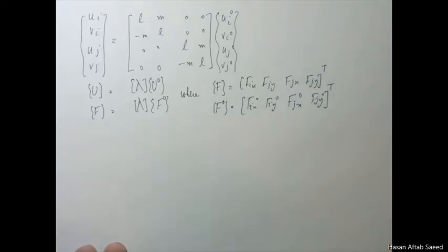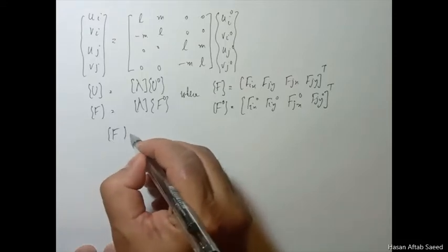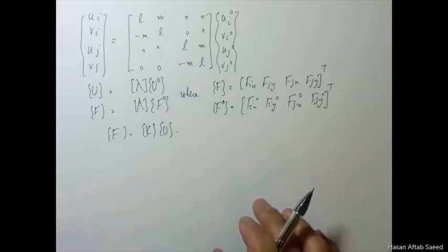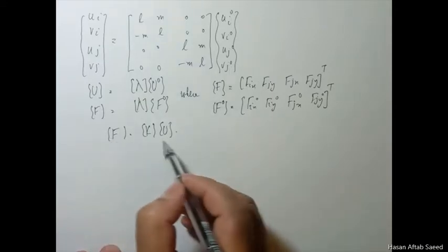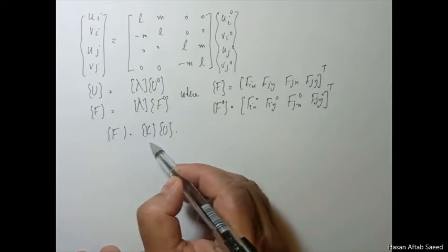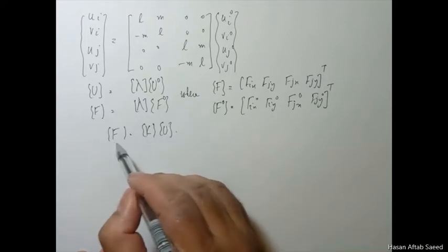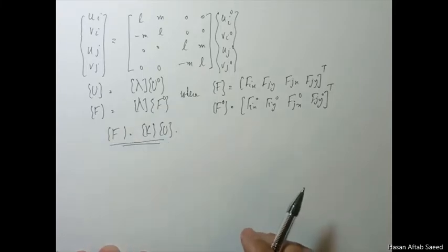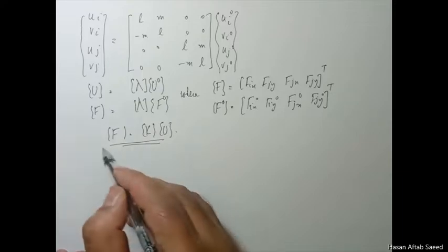Now we are very familiar with this equation in all FEM problems. Ultimately we get this solution. What sort of shape this takes, obviously it depends on the problem, but this F is equal to KU, this is basically the equation for a spring. And all systems, ultimately when you talk about stress analysis problems, especially problems where we are just talking about equilibrium problems, we are not talking about dynamic problems, then this is the shape.